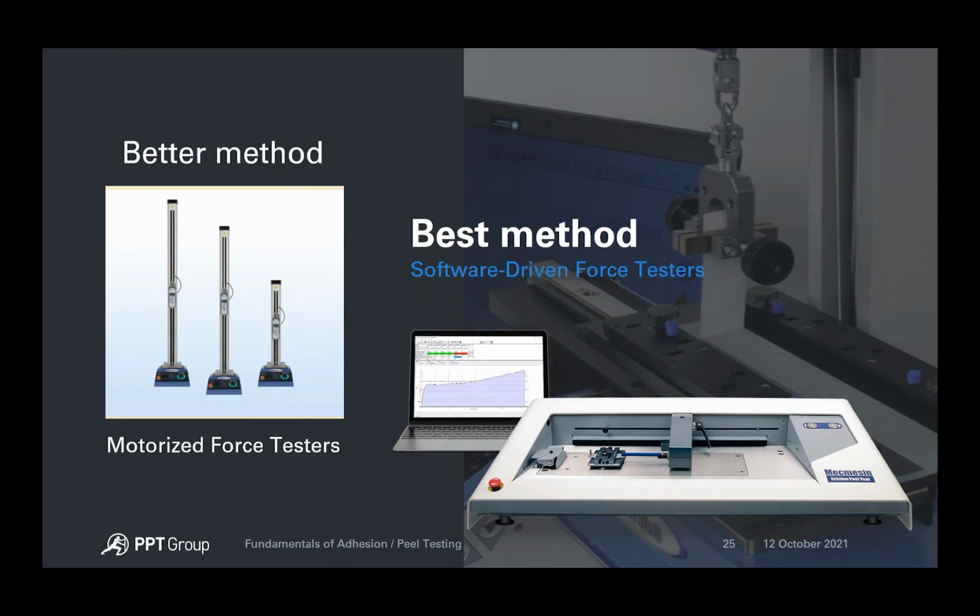So on to software-driven testers. While other peel testing options exist, the option that we highly recommend for this specific application is a software-driven tester. Software-driven testers allow you to not only configure and run the test, but also perform the necessary calculations per any specific industry standard or internal standard. Additionally, you can limit the operator to pretty much positioning the specimen in and out of the fixture and pushing the start button. That's all they need to do.